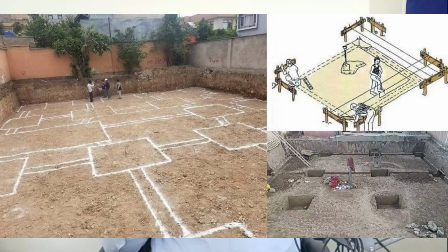After having that footing layout, you again do the excavation, only in the particular area where you are going to have your footing. There only you excavate. Up to what extent are you going to go down? You can take 1 meter, or you can say 3 to 4 feet. Up to that depth you need to dig. Okay. After digging that, you can have your footing.